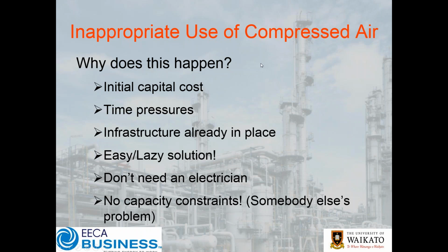Okay, so it's worth going back and talking about, well, why does this actually happen? Well, there are true cost and time pressures here. Capital costs of dedicated vacuum systems as opposed to just plugging into compressed air is a good one. Time, might not have had time, so it was looking for the quick, easy win we needed to keep the plant running. The great thing is the compressed air system's already there, the infrastructure's there, it's easy to tap in and use a bit more air. It's an easy, I call it a lazy solution.